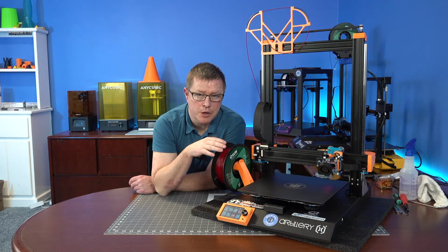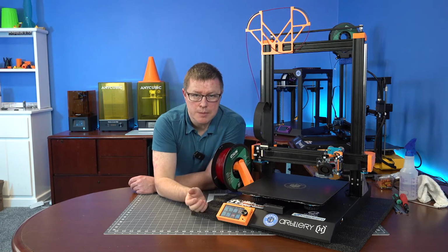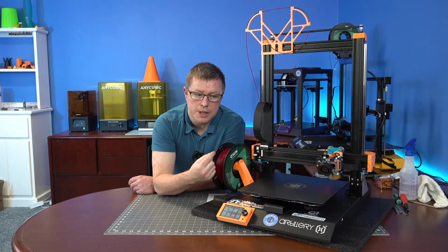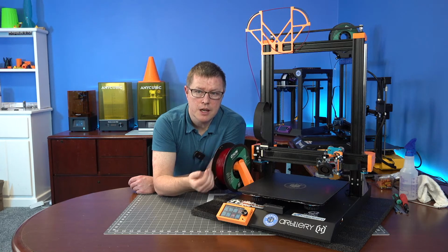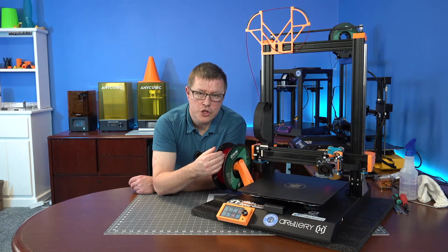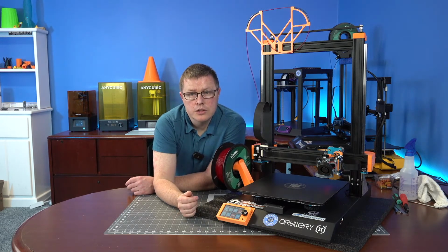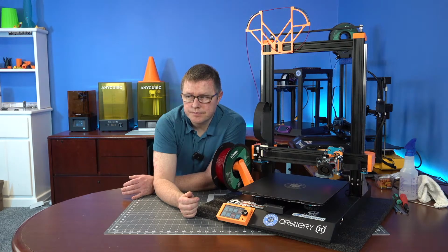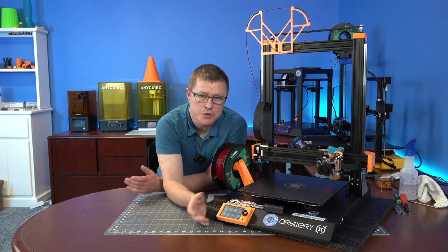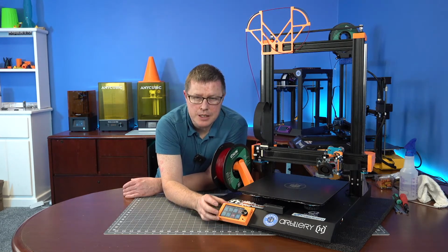So I've got it set up correct in Marlin, but it still gives me trouble. And then I used essentially the same setup on the X2, but on the X2 it has the new TFT and the new version of the firmware that has M600 enabled natively, and it works just fine. So there could still be some workarounds that I've got to think of with some custom G code and stuff. So I'm working on it, but I have a feeling it's a limitation of the TFT.